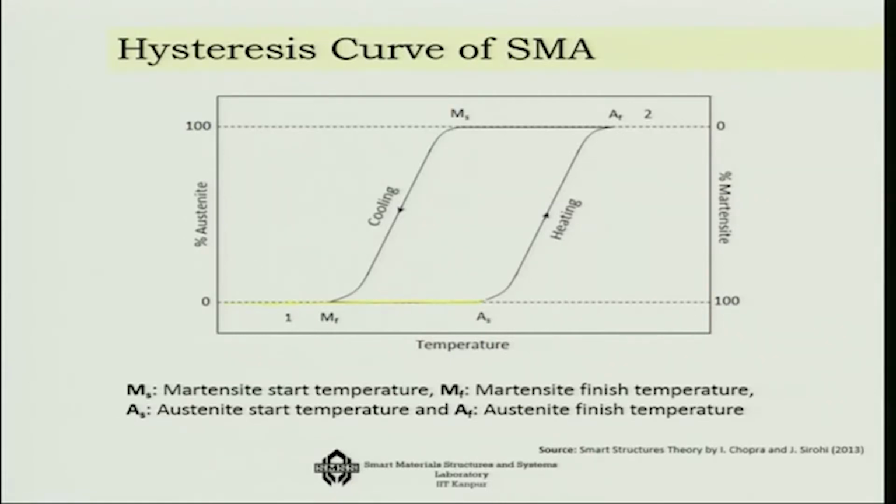formation, which is the FCC formation, and then as I am hitting this, the martensite is now getting converted and it is now becoming austenite. Okay. So, it is taking the BCC form. So, AS is where this is starting and at AF this is over, the austenite finish temperature. After that, if I increase the temperature, it will be 100% austenite. So, 0% austenite initially, and after AF it will become 100% austenite.